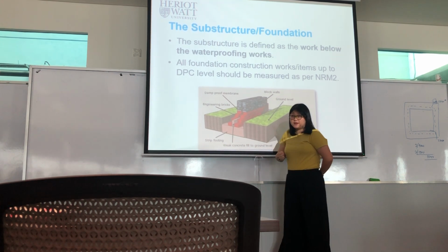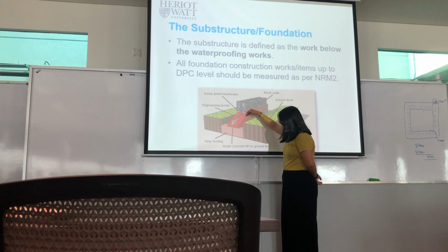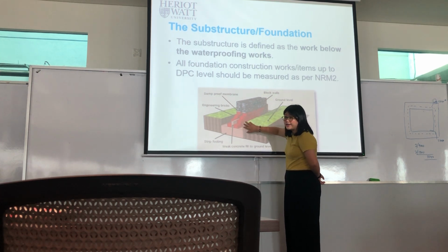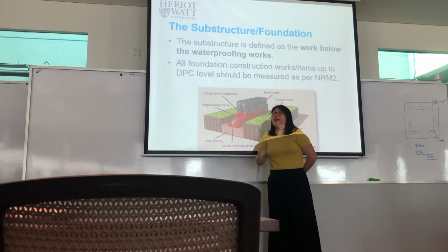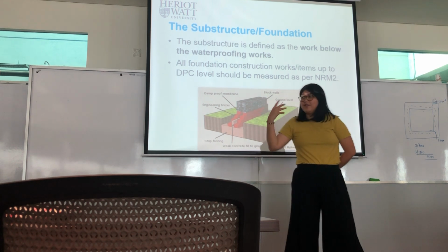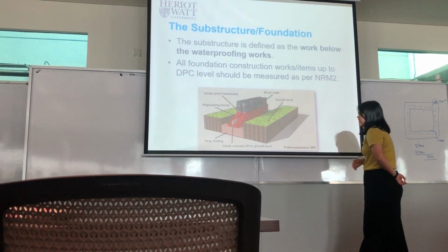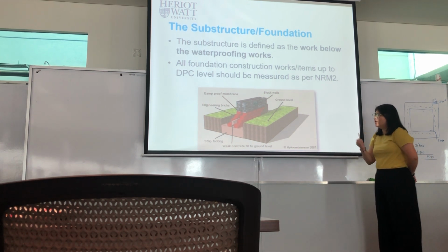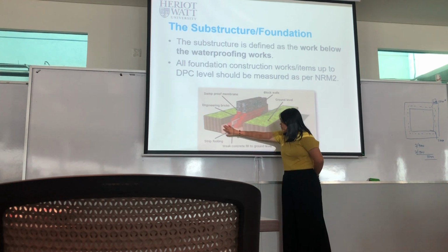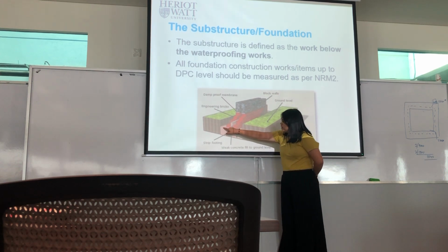Okay, so when you excavate this, if the soil is suitable, you will reuse the soil to fill in here for filling. That one you can save more money. But if the soil is not suitable, what do you do? You need to fill in with imported soil. And that is another, a different rate. Right? So there are so many items that you need to break down, dissect. That's why I say, being a QS, you must be very detailed and systematic, so that you know what you're doing. And you need to know the procedure.